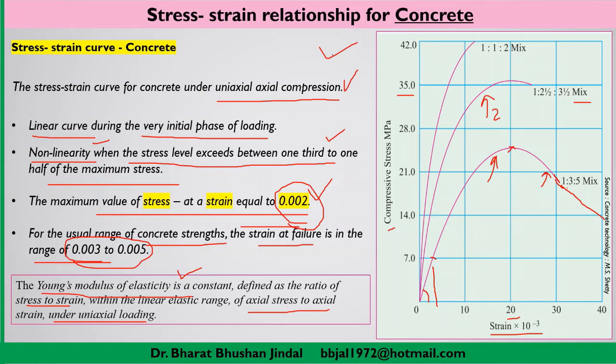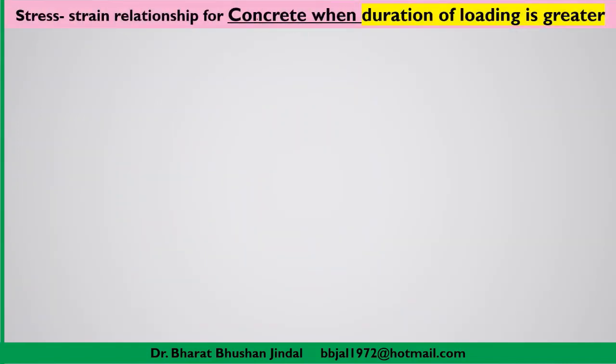But in general, when concrete is used in the construction, that means in the RCC structures, then that structure will be subjected to loading not only for 10 minutes, but maybe for 1 year, 2 years, like that. So now we have to understand the stress-strain relationship for concrete when duration of loading is greater.